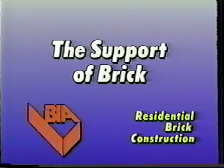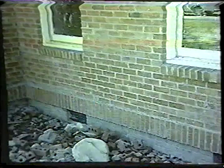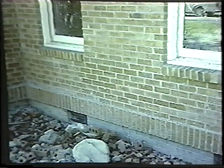The support of brick. Brick must be properly supported by foundations or structural members in order to prevent cracking or stability problems. In some severe cases, the result is the masonry falling off the house. Not only must the brick have sufficient bearing, but steel lintels supporting the brickwork must be properly attached to the structure. Here are some indicators of improper bearing conditions: bowing walls, cracked mortar joints, or cracked units.